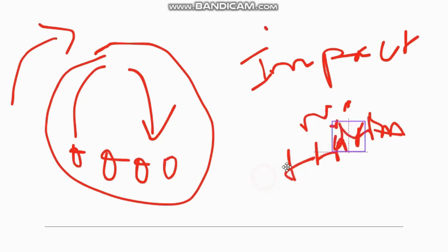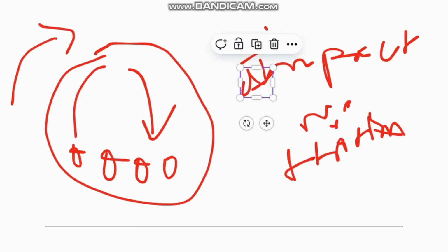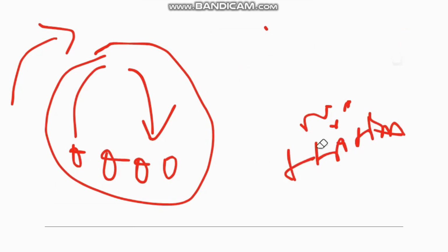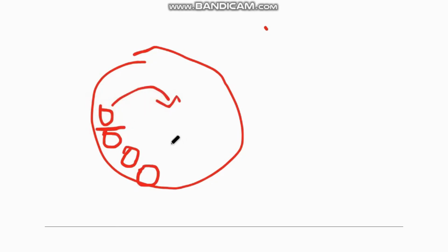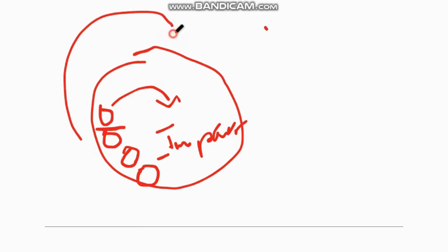Then if the cylindrical vessel is rotating at a very slow speed, then also the size reduction will not take place efficiently, because due to slow movement of the cylindrical vessel, the balls will only be lifted slightly. Only the attrition will take place, and there is less impact mechanism, due to which the size reduction does not take place in an efficient way. So to avoid this, we have to run this vessel at an optimum speed.